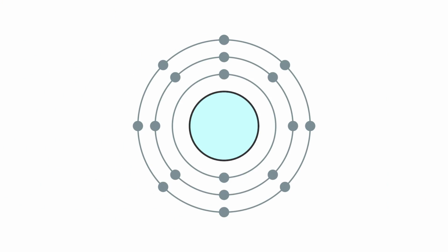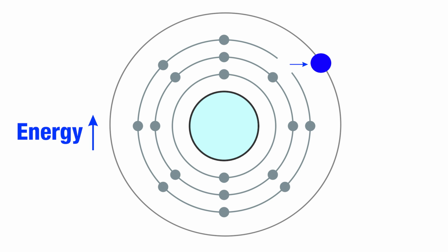All right, so now we have some context, but what does that have to do with OLED? Well, everything. You see, molecules used in OLED are special because they emit light when a current is passed through them. How this happens is when current passes through them, it adds energy which is absorbed by those molecules and their electrons. This extra energy kicks some electrons into a higher energy layer of the electron shells, known as the conduction layer. When this happens, this leaves an electron hole in the lower energy level, or the valence shell, where the electron was. Simple enough.